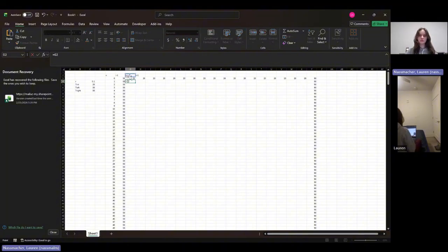Our temperature at our spatial node I plus our R value, our key parameter, which we can change later but which will remain constant throughout the spreadsheet. So we want to put $ signs in front of that number in order for it to remain constant, and we can change it later to determine at what point it makes the temperatures unstable. It's going to be multiplied by our temperature at our spatial node -1 minus 2 times